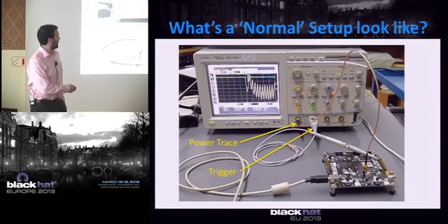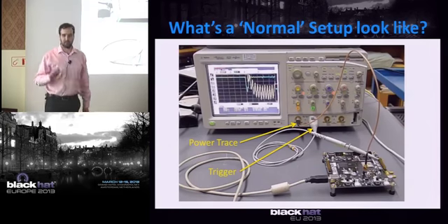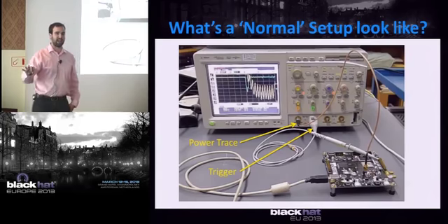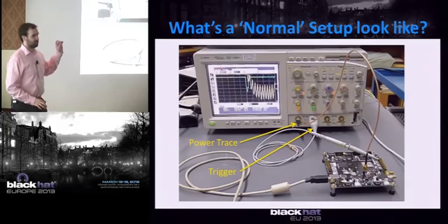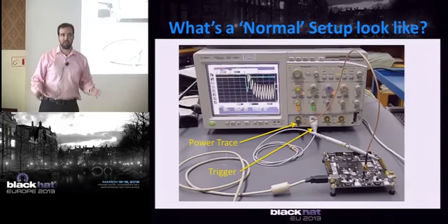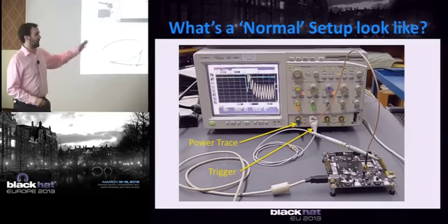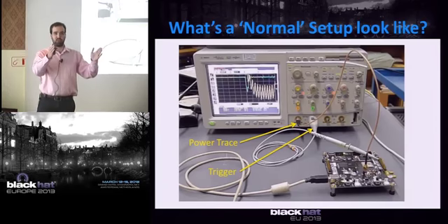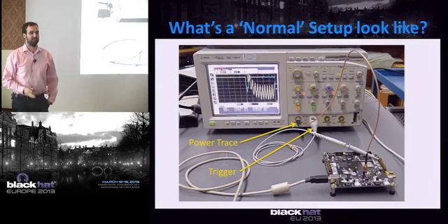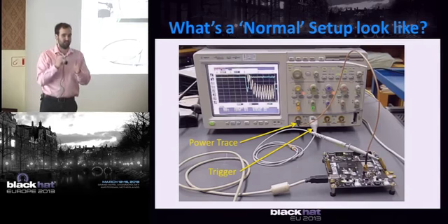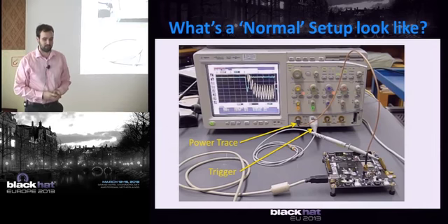It has a trigger pin. So what this trigger does, and I'm doing the same sort of hack here, is tell you specifically when the AES is occurring. You might have noticed in that plot I had, I said, well, way over here in this window, this is where the actual operation is occurring. I had to acquire a whole bunch of points because I didn't know where the operation was going to occur.